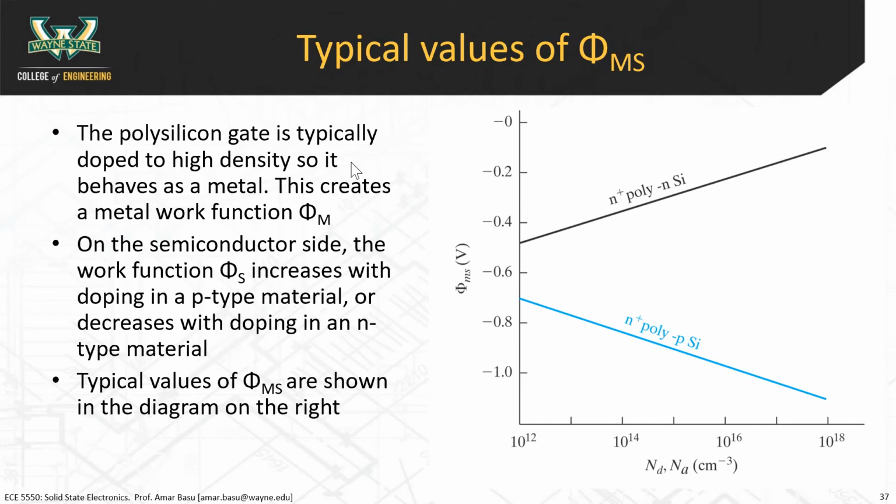The issue with the metal is that it has to be able to withstand high temperature processes. Some of the earlier processes used to make the source and the drain regions, and ultimately the oxide regions, and then the gate, and then the additional metallization layers, some of them required high temperature processes, and a lot of metals can't withstand high temperatures. For example, aluminum melts at high temperatures.